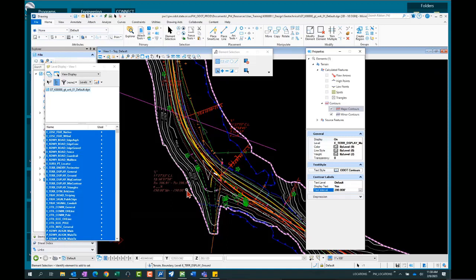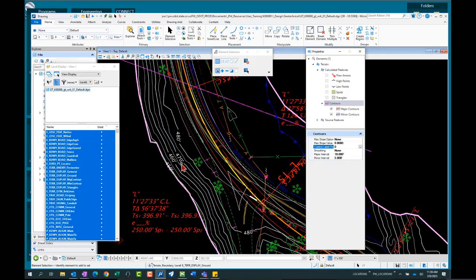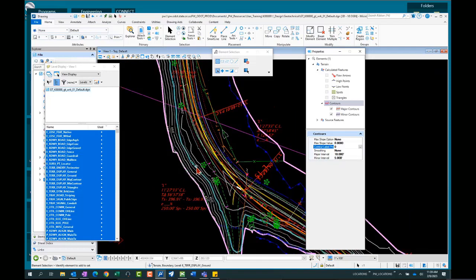That's kind of cool. I'm going to go back to the contours parent group, and I'm going to change the contour label precision to 0. And now it no longer shows me the dot 0. This stuff will all print, and that's an easy way to print things. Just wanted you to see how to create your own contour.